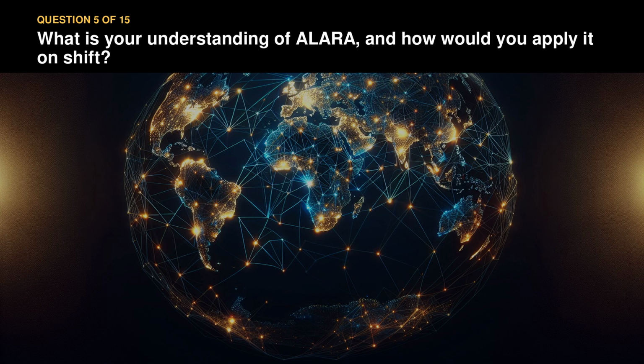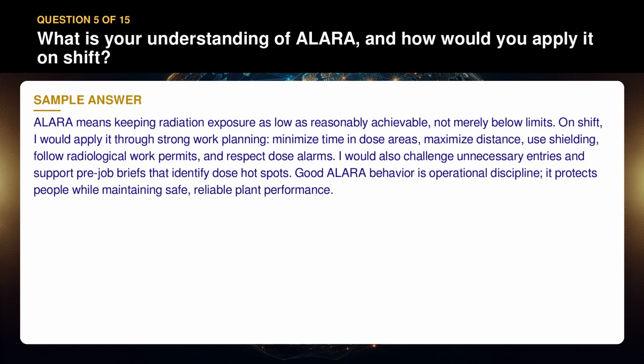Question 5. What is your understanding of ALARA, and how would you apply it on shift? ALARA means keeping radiation exposure as low as reasonably achievable, not merely below limits. On shift, I would apply it through strong work planning. Minimize time in dose areas, maximize distance, use shielding, follow radiological work permits, and respect dose alarms.